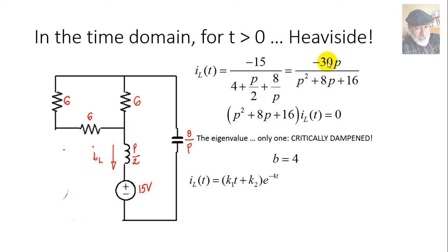What about k3? What of the steady state of that current? You say, well, in that RLC series circuit, the final value of the current is bound to be 0. We have a DC source. In the end, the capacitor will be fully charged and the current will not flow anymore. So that is our current.